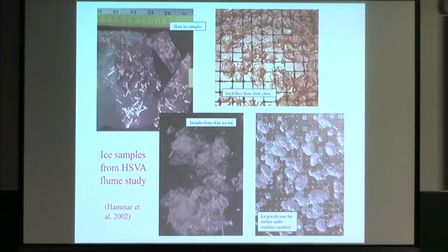And then when you go into a mainstream or higher velocity, they begin to cluster, or could be even bigger and bigger if you are in a rapid. And actually in the rapid you see ice balls this big from frazil ice.